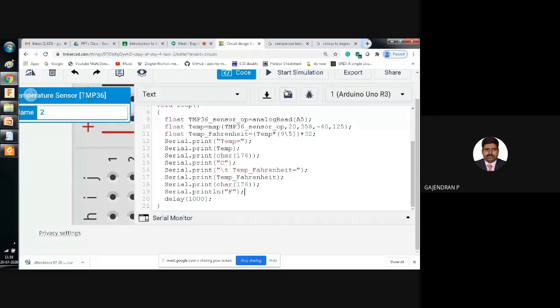See, you know that only at minus 40 degrees Celsius, the Fahrenheit reading and Celsius reading will be the same. If you want to cross-check the formula you have given, we will keep our temperature sensor at minus 40 degrees Celsius, then we will check our output. Okay, now I'm going to start the simulation. Please check the output.